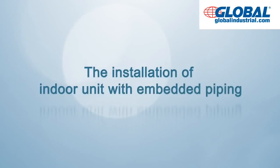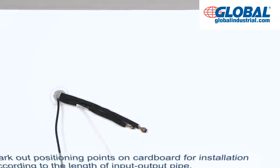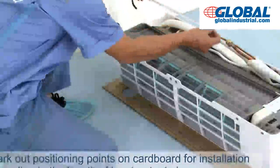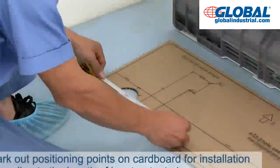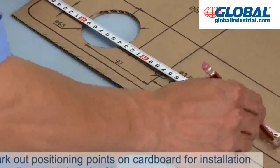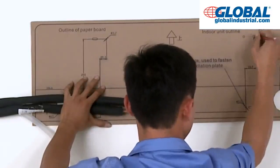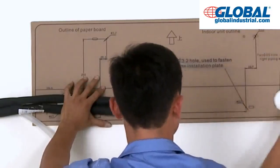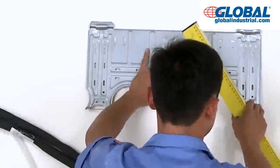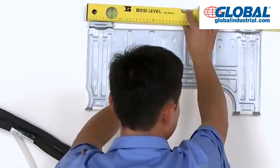The installation of indoor unit with embedded piping. Firstly, mark out positioning points on cardboard for installation according to the length of input-output pipe. Make position on the wall with cardboard, according to the position of embedded pipeline and the cardboard positioning point. Determine the installation position of indoor unit.